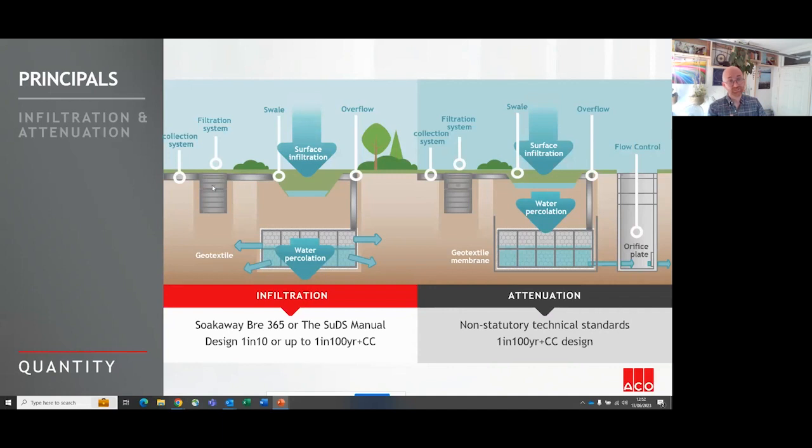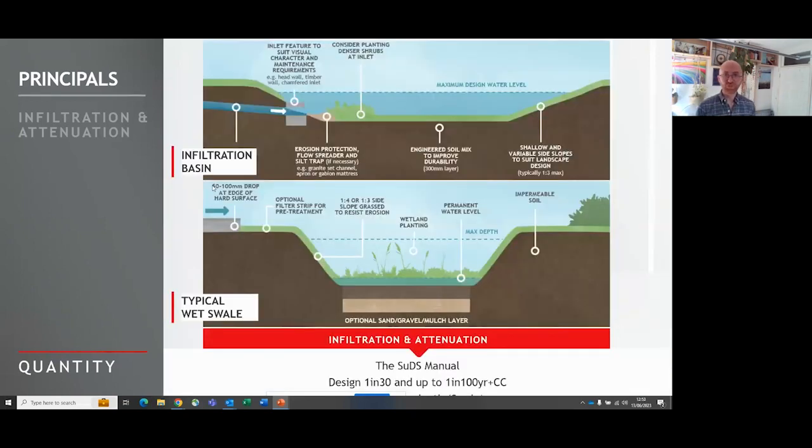the system. In the example on the right-hand side, you can see that they've got high overflows, so you try and put it into the natural environment first, in a pond or a swale or a bioretention centre, and then the overflow would go down into an underground tank or into some other system. So it flows and creates this kind of chain where you've got the storage happening at different points, creating differing environments along the process. So infiltrate or attenuate.